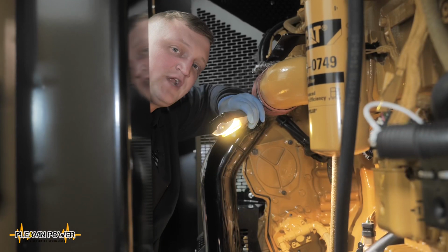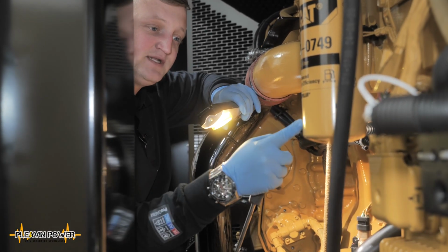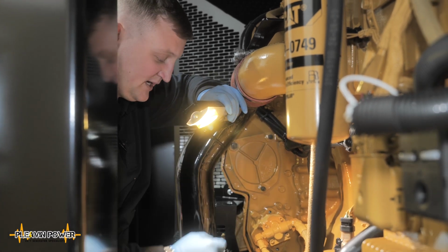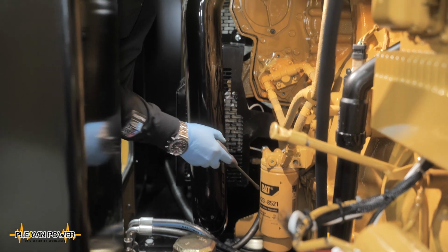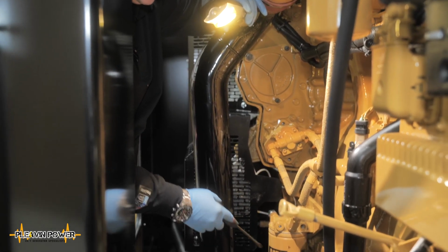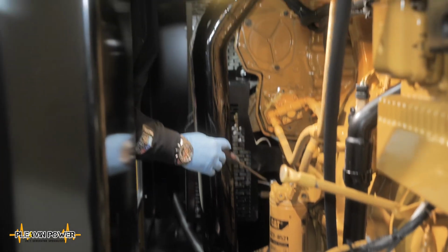Let's move on to what should I be getting in my maintenance and service contract. One thing you should be ensuring is that your primary and secondary fuel filters are being changed, and that the main engine oil filter is being changed, which is on the opposite side of this engine in this case. These primary and secondary fuel filters need to be changed on a regular basis to prevent the top seals becoming dry and the filter becoming attached to the filter housing itself.